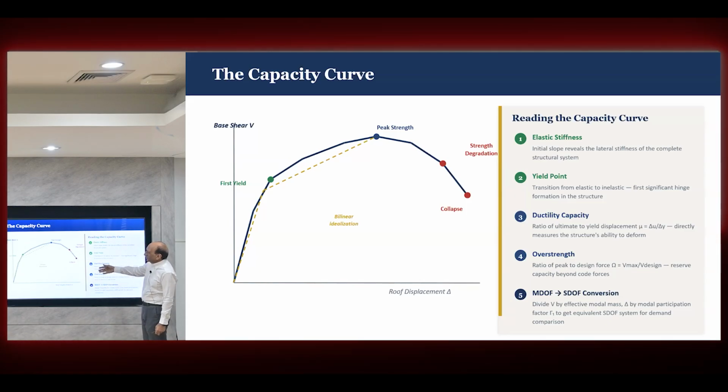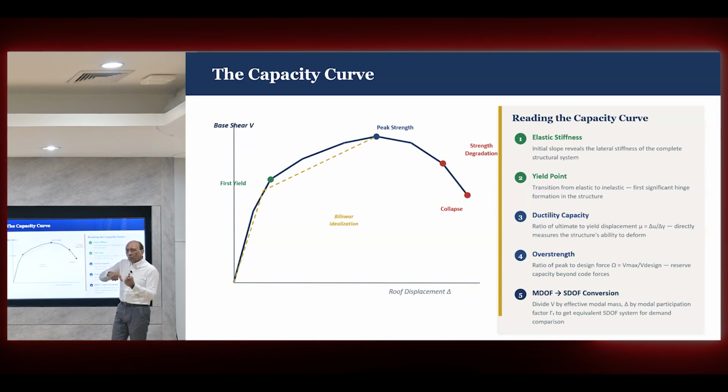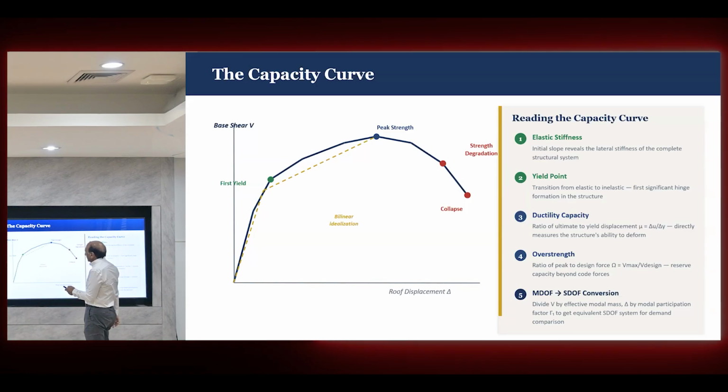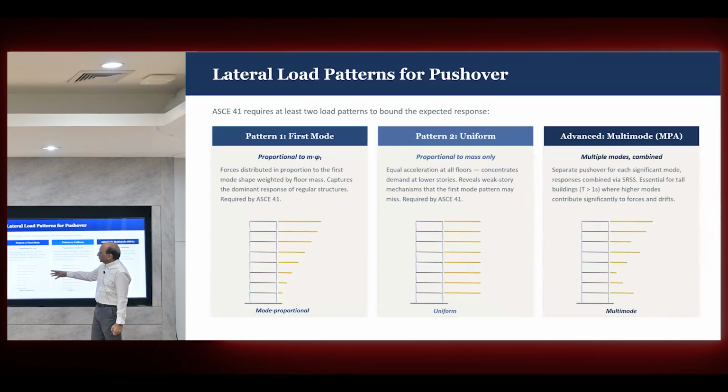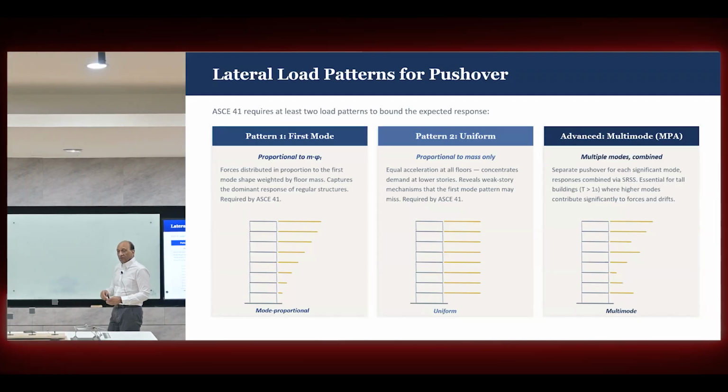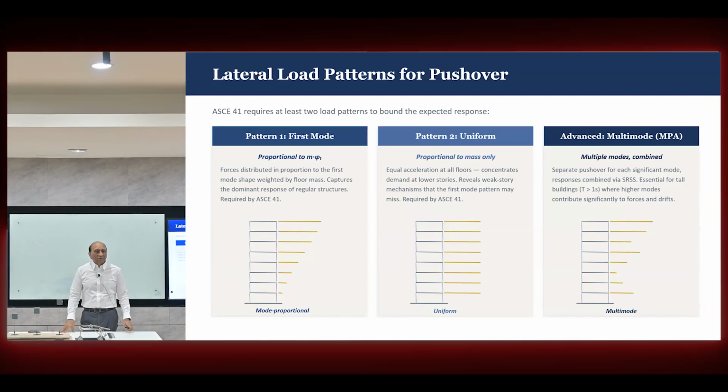And now we bring those concepts again and apply them to the whole structure. Before, we applied them just to one cross section. Moment curvature is one cross section. We now apply it to the whole structure. So basically the codes require that you apply the load in a certain manner. You cannot choose the pattern. The force value is not specified, is not known, but the pattern has to be selected.